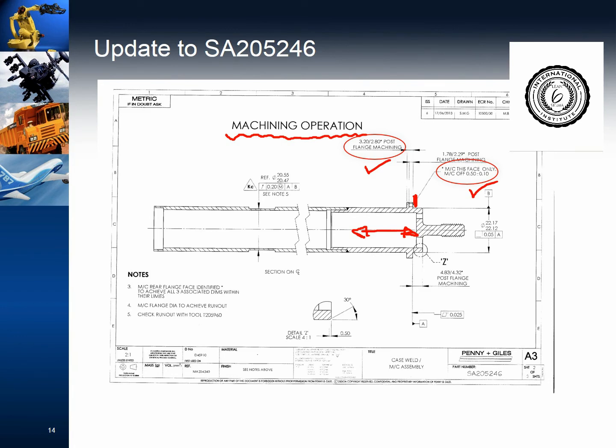However, it turns out those faces are the datum face for the jig that we saw earlier. So when the part is placed in the jig and then we try and measure the datum of the shaft that's running through the center, this is the datum face right here. And what we've done is moved the datum face because of some other requirement.